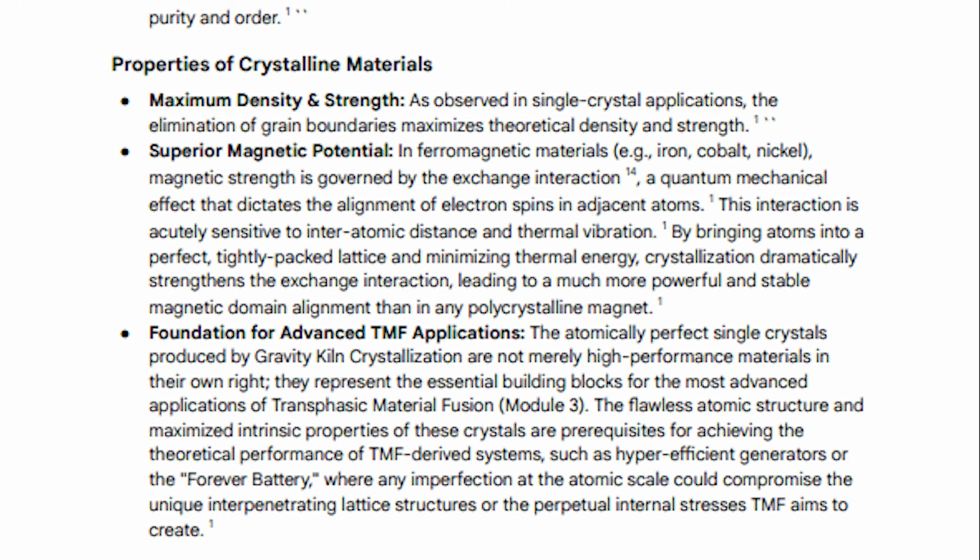This interaction is acutely sensitive to interatomic distance and thermal vibration. By bringing atoms into a perfect, tightly packed lattice and minimizing thermal energy, crystallization dramatically strengthens the exchange interaction, leading to a much more powerful and stable magnetic domain alignment than in any polycrystalline magnet.